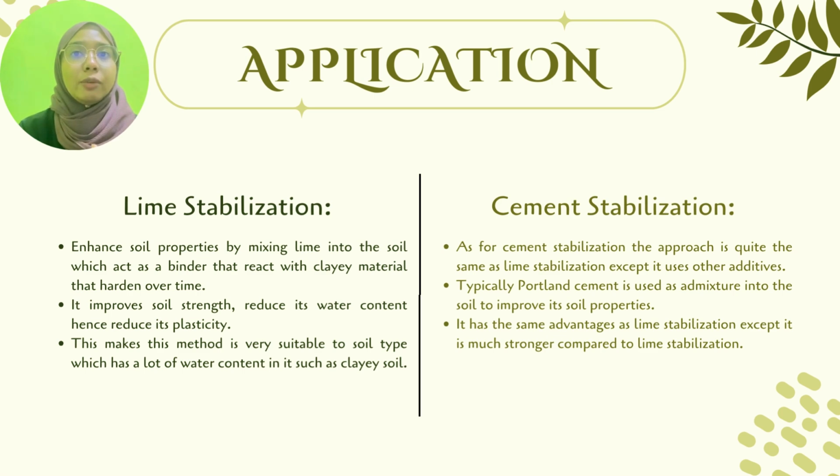When lime is combined with clay, it will react with soil particles and permanently transform the clay structure into strong cementitious materials. It will also reduce the water content in the soil and the plasticity of the clay, which allows engineers to compact the treated clay very well. This makes the method very suitable for soil types which have a lot of water content in them, such as clayey soil.